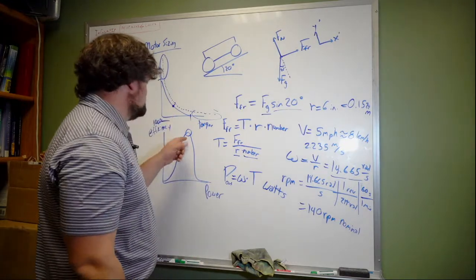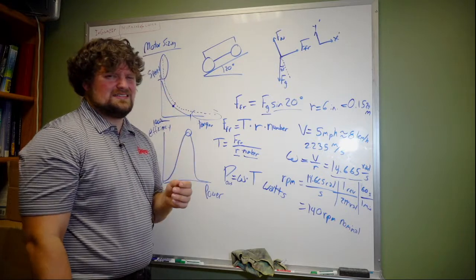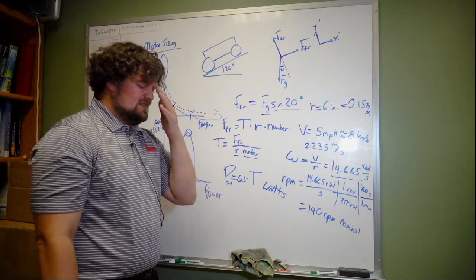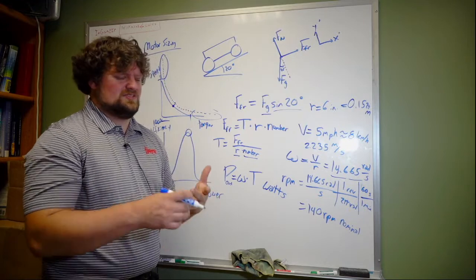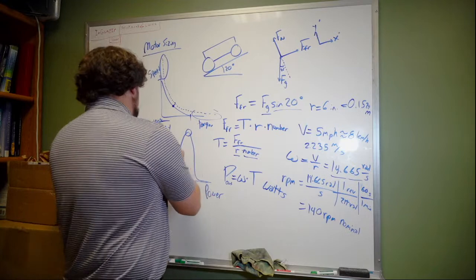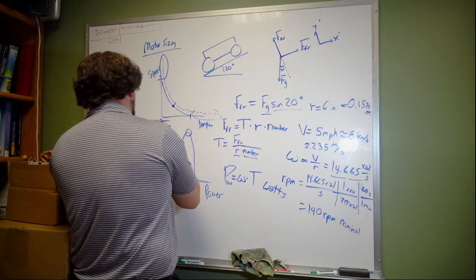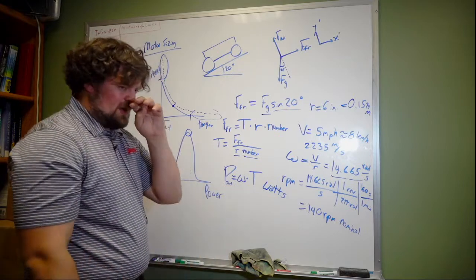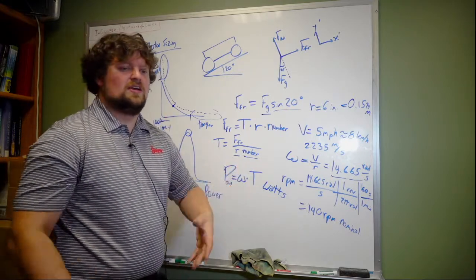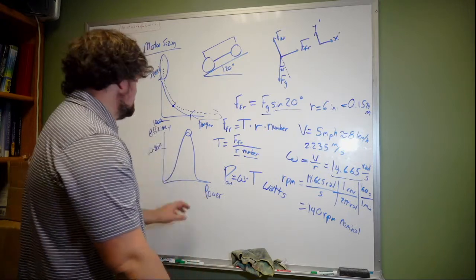The most efficiency we can get out of electric motors, I think we've seen some that get like 96% efficient. Under certain conditions, they have to be at a certain speed and a certain torque. Typically what I expect out of these though is somewhere between 60 to 80% efficient. If you operate off of an 80% efficiency expectation, usually that's good enough. And that's what I'm going to do.